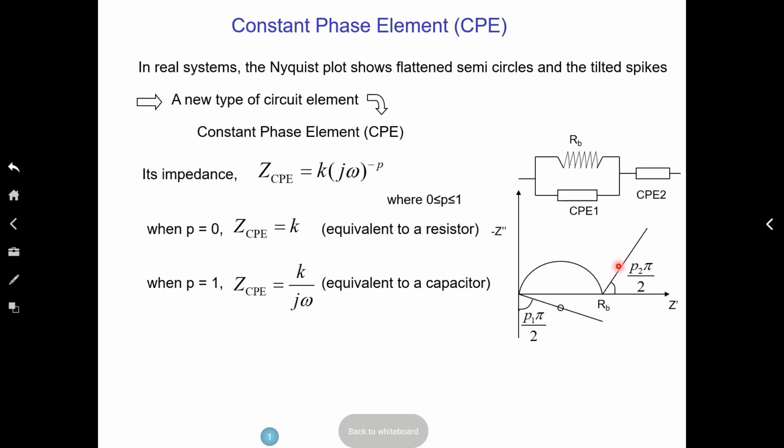Ideally you want platinum particles connected with a lot of porosity. Why do you need that? You need all this porosity for oxygen to be able to come in, with the so-called triple phase boundary, TPB.